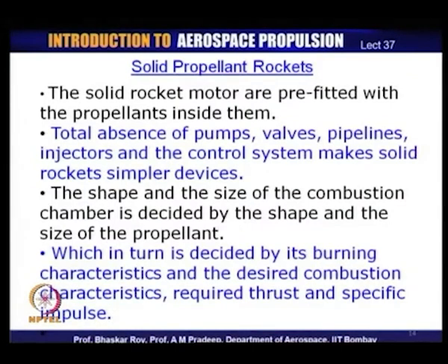Now, the shape and the size of the combustion chamber is decided by the shape and size of the propellant. This is unlike a liquid fuel, where the shape and size, as we just saw, is decided by the combustion characteristics and the fuel characteristics. But here the shape and size is decided by the shape and size of the rocket propellant itself, which needs to be given a particular shape and a particular size. We will have a look at some of these shapes in a few minutes.